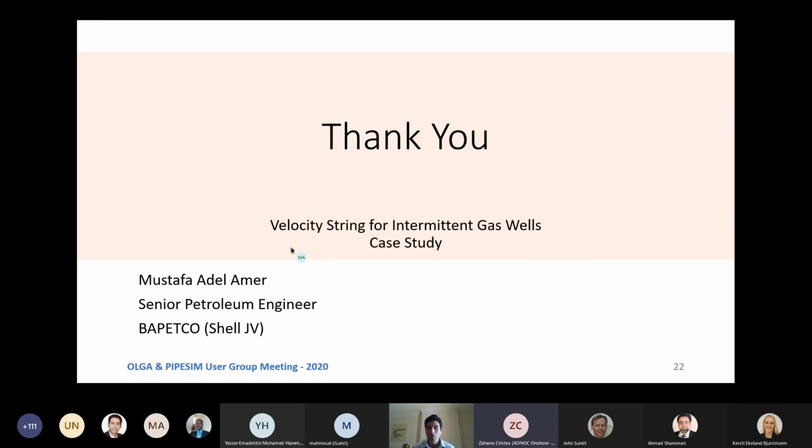Okay, all right. Because there might always be a problem with the packer leaking and building up some pressure in that space, and then you might have some integrity issues. A good thing is that in these wells the reservoir pressure is quite low. The reservoir depth is 4,000 meters, and the reservoir pressure is around 1,400 to 1,500 psi. All right, so not a big concern.